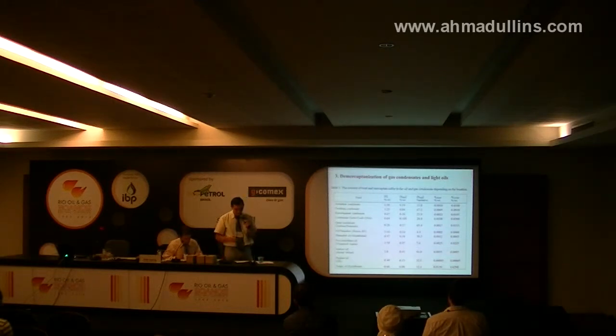The share of mercaptan sulfur in a number of fields ranges from 12 to 67 ppm weight. So we can see that for Qatar condensate, for example, we have 65% of mercaptans by weight of total sulfur. For Zanazol oil, Kazakhstan Republic, and others.